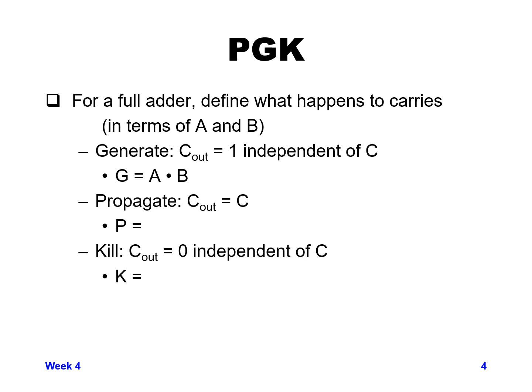Second thing is, how do we figure out if we do need to propagate the value of carry in to carry out? And that would be true if the XOR of A and B is true. So if either A or B is a 1, but not both of them, then we know we need to wait for carry in to come in to see if carry in is a 1 to decide whether to send a carry out.